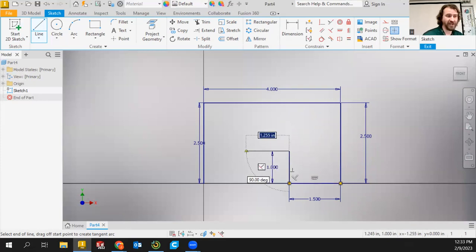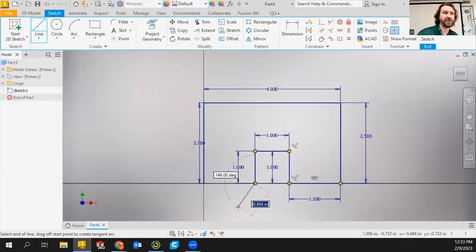And again, I'm typing these fairly quickly, mainly because I'm typing this in and I'm getting the line kind of where I need it to go already, making sure that it's straight, perpendicular, making sure it has all those values other than the dimensional length. And then I can just type in the dimensional length and hit enter because I've seen the other constraints already in place. So the last line here, again, is just connecting back to 0, 0.